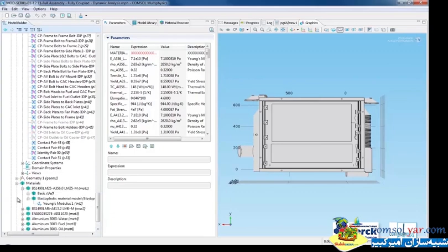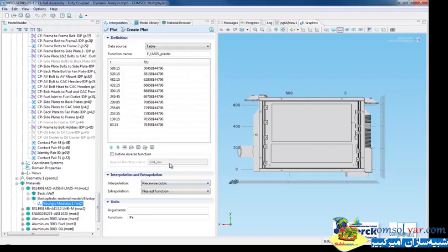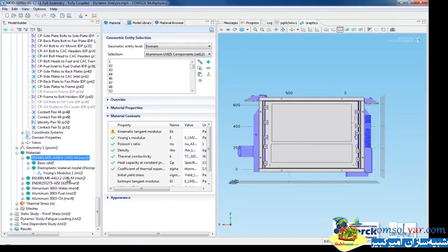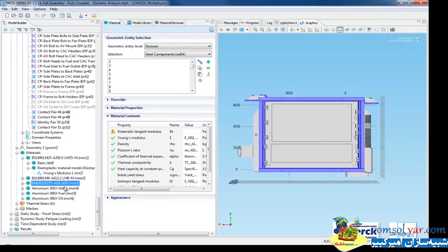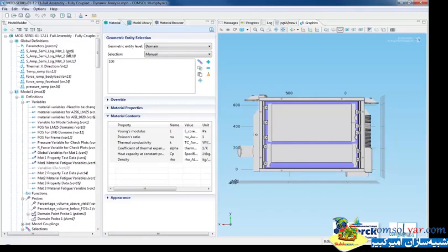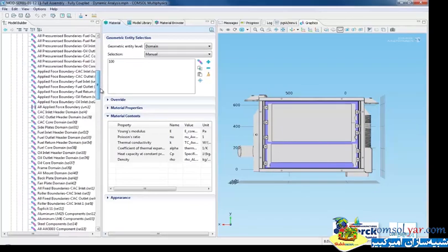Having so many components, each operating at different temperatures, the material characteristics are not easy to set up for thermal fatigue. Thanks to COMSOL, using the function feature inside the material section, we can make material characteristics temperature dependent. Having made the selections before and with the material parameter set, implementing the material properties for different components is made even simpler. Since we performed fatigue analysis of the system, we also have S-N curves set up to help us analyze the fatigue life under various loads.